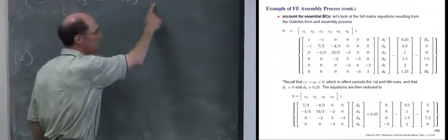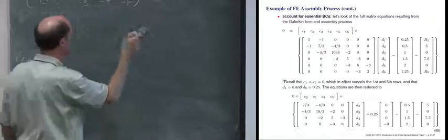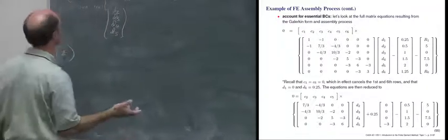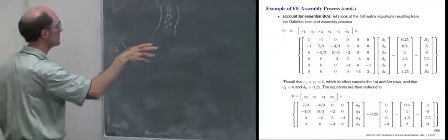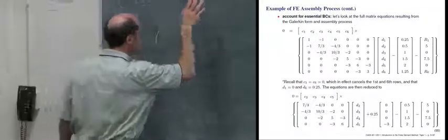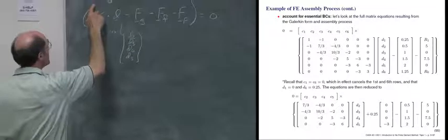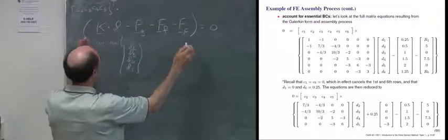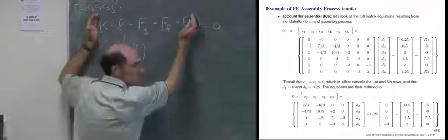That's what our weak form told us from the strong form, and then from the discrete approximation to the weak form to the Galerkin, and then we did our interpolation functions. So if this equation must be 0, and this is arbitrary, then the only way this equation can be satisfied is if what's in the parentheses is 0.